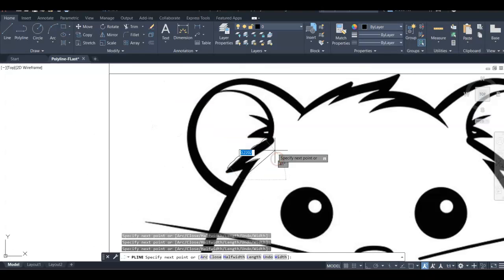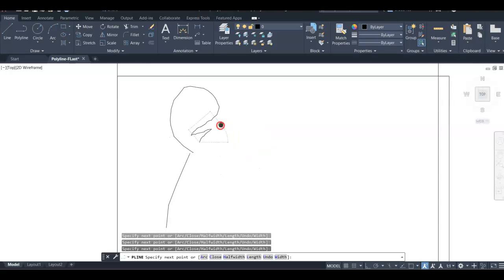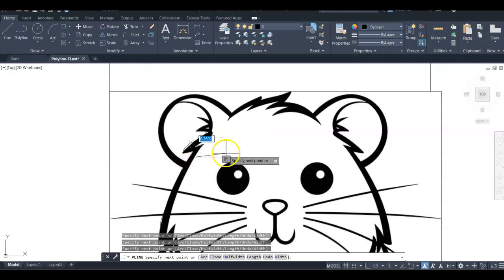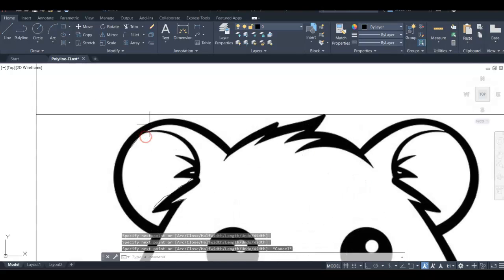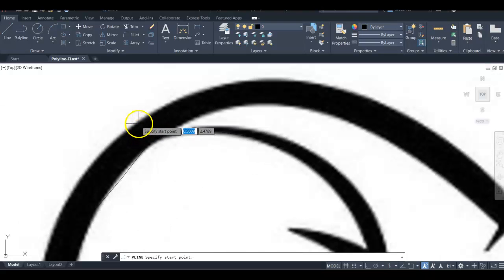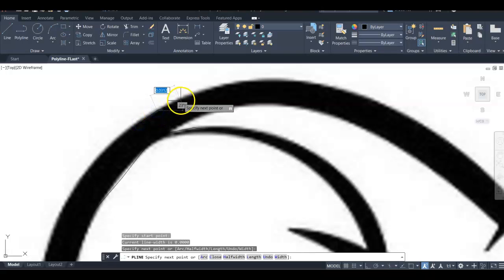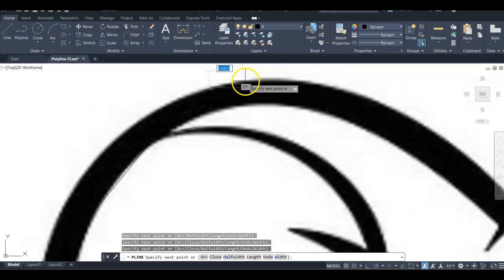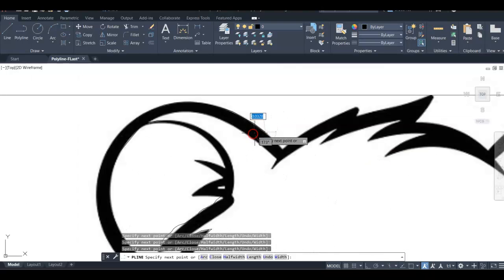To double check, again, I'm just pressing and holding the roller track button so I can see where these lines are at. So that's all I need to really do in order to create the polylines. Take your time, so zoom in on these and really take the time to trace. You're just using polyline here to trace out the lines that you have inserted into your drawing. So that's all we really got to do when we're creating this particular file.